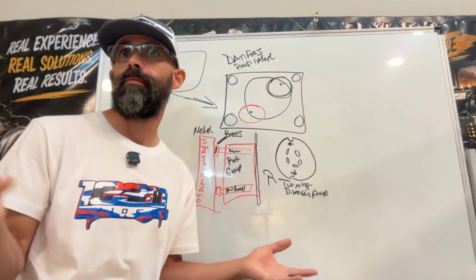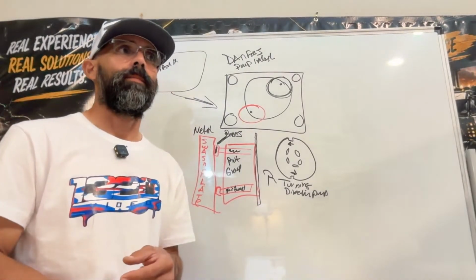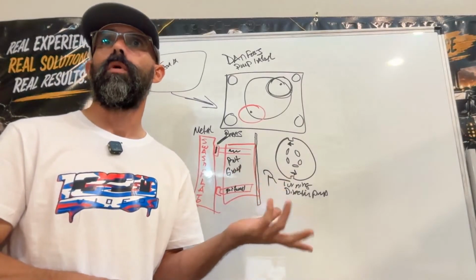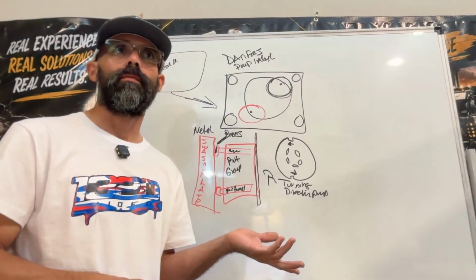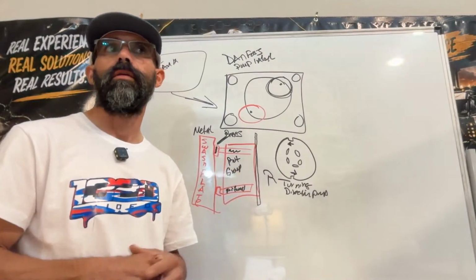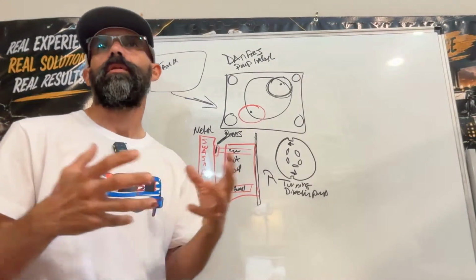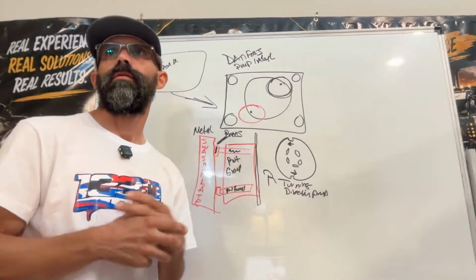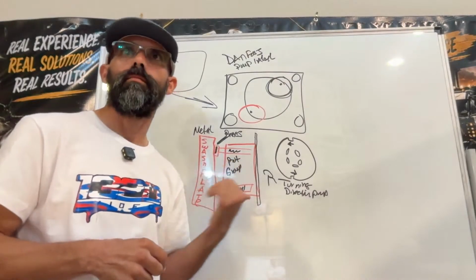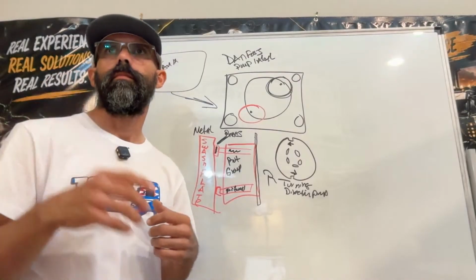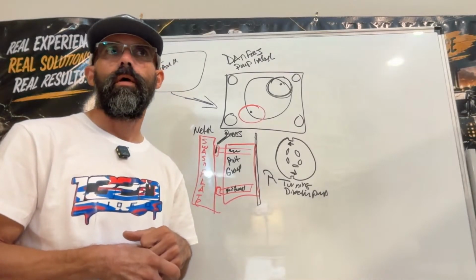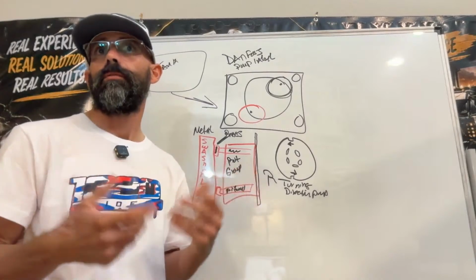I've seen rocks. I've seen glitter from maybe a hydraulic motor that blew up, or broke up and ended up in the pump. I can see different symptoms and causes that made the pump fail and need to be repaired or rebuilt.